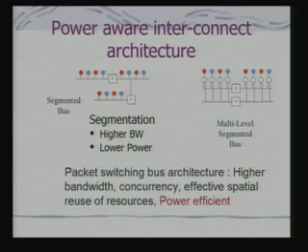Next most important component is your interconnect, the bus. And the bus is also another source of power consumption, because signals have to flow. In many cases, power supply has to be provided, and if things are connected via wire in a bus, there would be power consumption in the interconnect. So, the issue becomes that of dealing with power consumption in the interconnect.